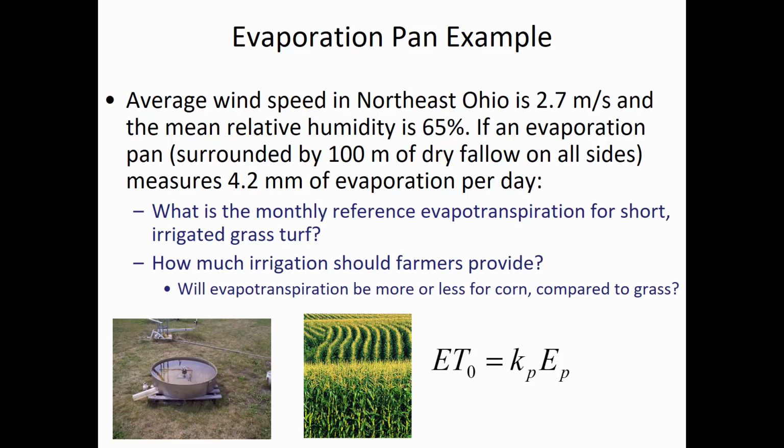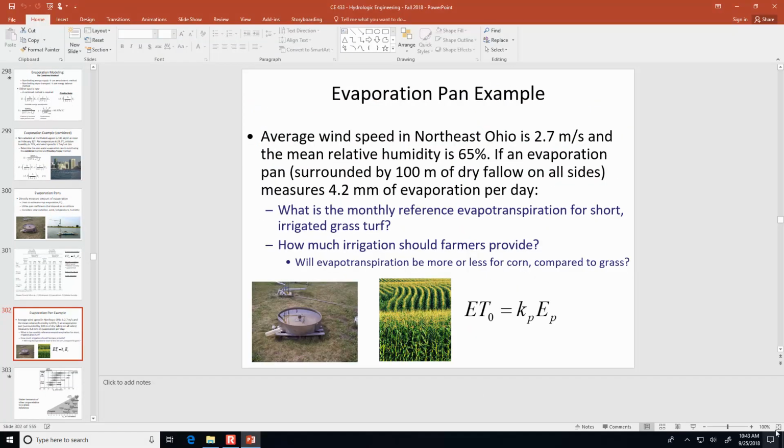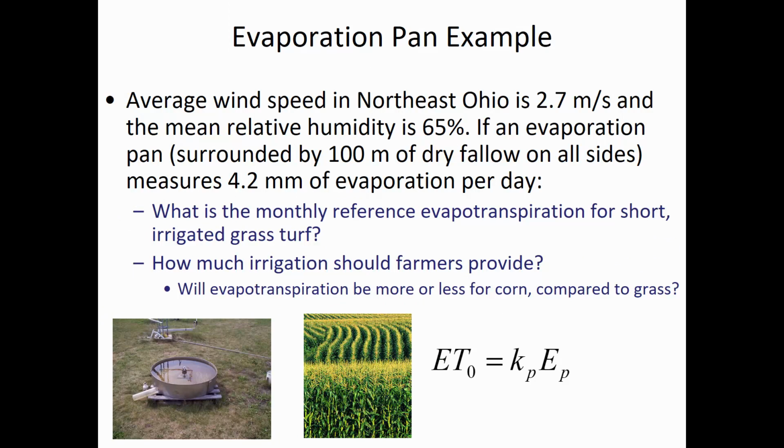Could you also measure the transpiration by having two pans in the direction of wind, one before the crop and one after the crop? That way you can see the difference in evaporation rate between the transpiration. That might be one way of looking at it, but remember, if we had an upwind and a downwind, some of the moisture might be going up rather than just only side to side.